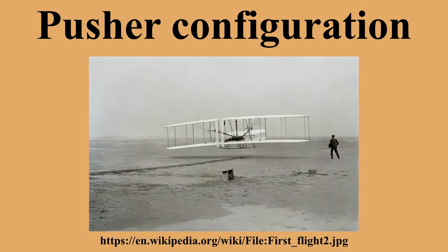Engine installation considerations. In a pusher configuration, the force provided by the propeller is pushing towards the engine, rather than away. To convert a tractor engine and propeller combination to pusher operation, it is not sufficient to simply turn the engine and propeller round, since the propeller would continue to pull, driving the aircraft to the rear.